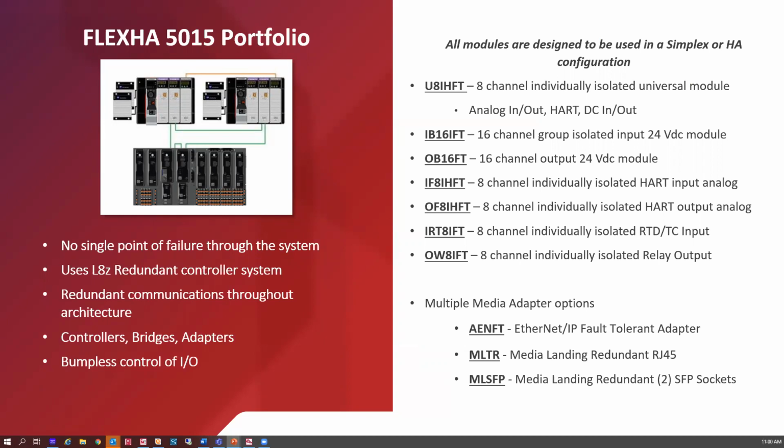And this is going to help us, especially on the networking part. We will have 2 separate comms adapters to be able to run to. So we can easily do a PRP or a DLR type network off of it. And the redundant backplane really will be able to give us a nice fault tolerant IO solution. So this is something to look forward to, and we will also be able to take fiber directly to this chassis.